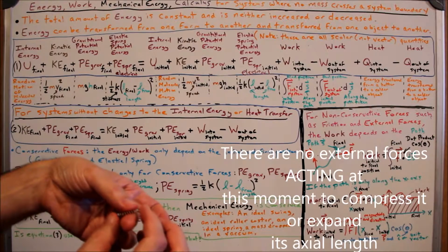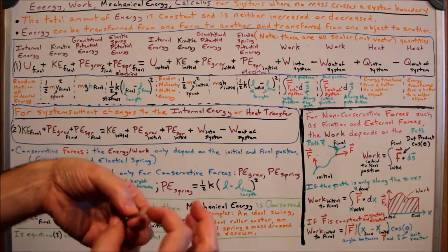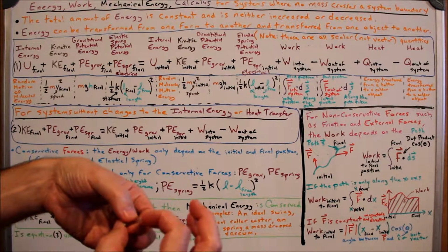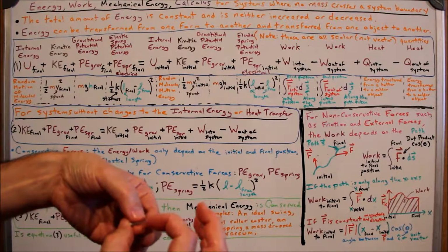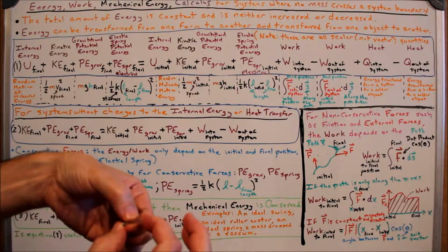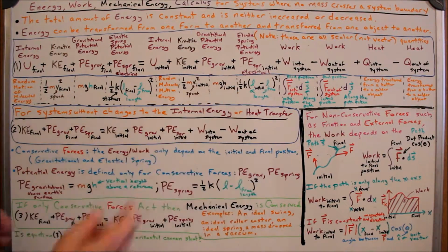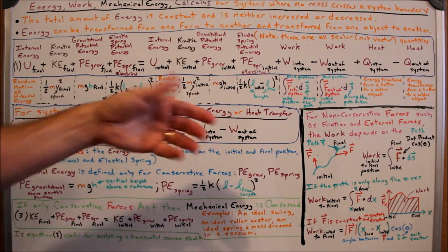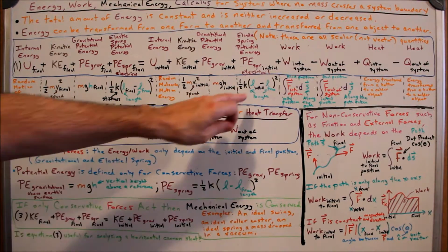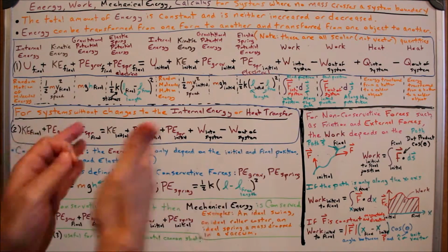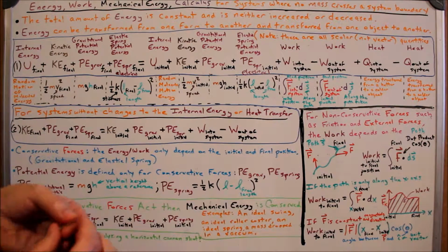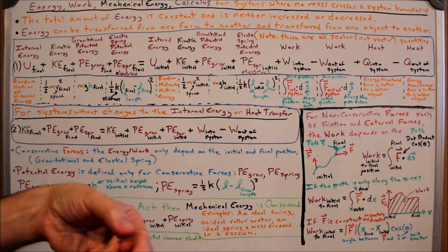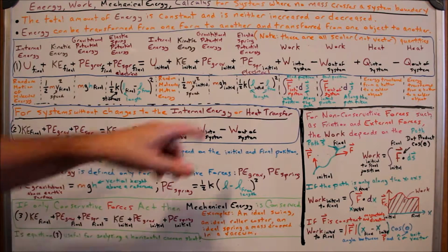And then if I put a force acting on it axially, so if I push in on it, its length changes, and it takes a force for me to move that. We'll talk more about k later in another video. That's the stiffness of the spring, the ratio of the force divided by the deflection. For example, that could be pounds per inch, so how many pounds it takes to deflect an inch, or newtons per meter, or some other value.